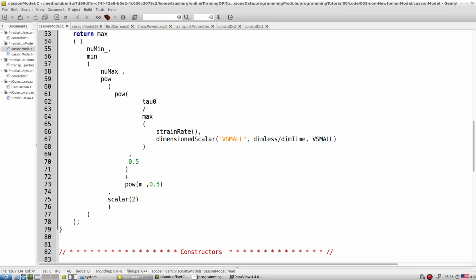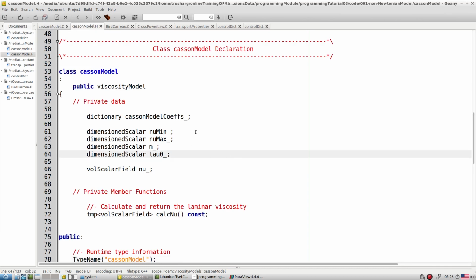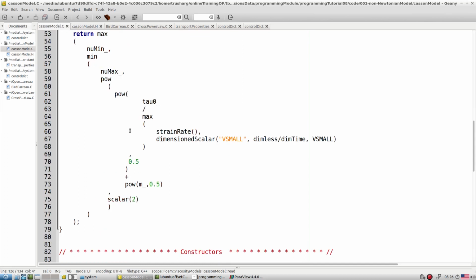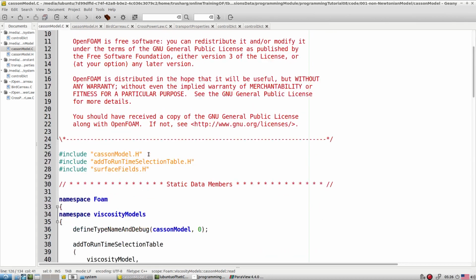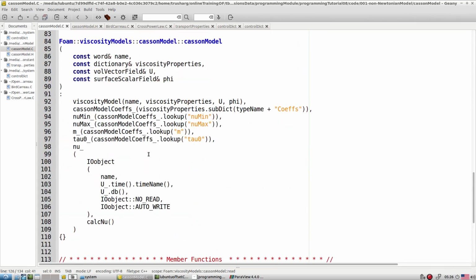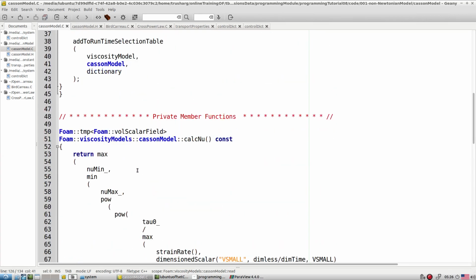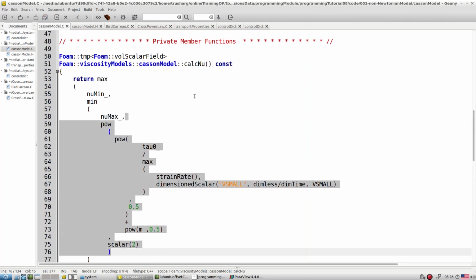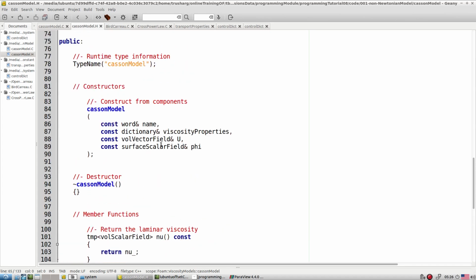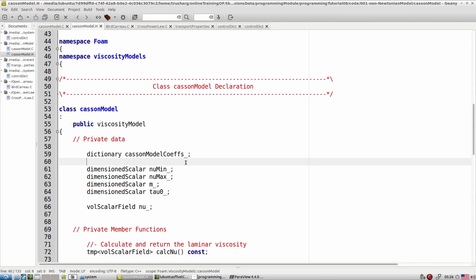When you want to start new development, don't do it all at a time. First, don't remove anything. First only establish a new variable, whatever you think is needed for your calculations, and finish in the .H file and the .C file. Then compile again. Then develop the code you want, and compile again. If everything went fine, then whatever variable is not used, later you delete it, and then we are set with the library.